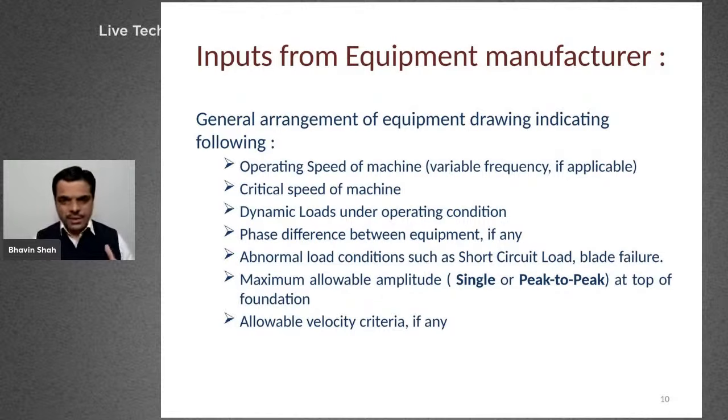Now if it is given at a certain height, then we will have to make certain pro rata calculations and so on. So instead of that, we always ask that please give the maximum permissible amplitude at the top of the foundation. And if it's not clarified in the drawing, then we understand that it is at the top of the foundation, and if it is not at the top of the foundation, then please provide the relevant permissible amplitude. One more area in this is whether it is single or peak to peak.